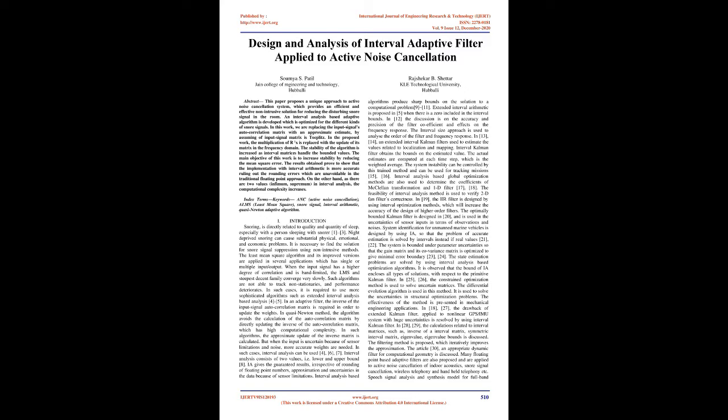The least mean square algorithm and its improved versions are applied in several applications which have single or multiple input/output. When the input signal has a higher degree of correlation and is band limited, the LMS and steepest descent family converge very slowly. Such algorithms are not able to track non-stationaries, and performance deteriorates. In such cases, it is required to use more sophisticated algorithms such as extended interval analysis-based algorithms 4-5.